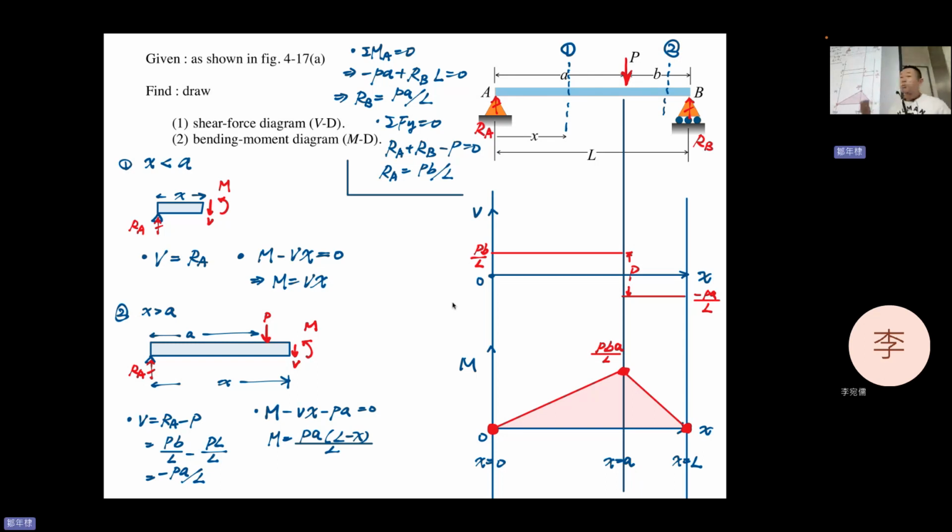Of course, because remember that our hinge and roller cannot take any moment. So if you have a moment here, can it take it? Of course not. This moment is in the material, so if you have a hinge here, the material cannot handle the moment. If you have a non-zero moment here, well, it will rotate like hell. Okay, if you're using the hinge.